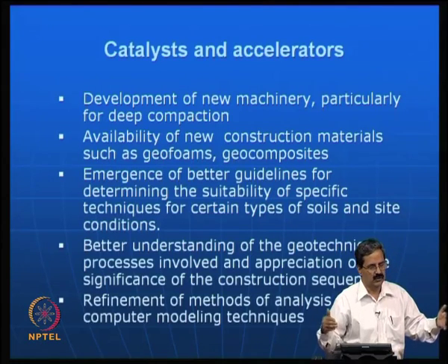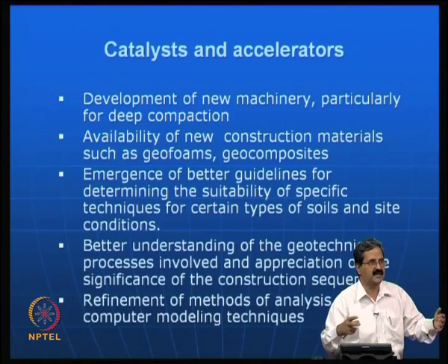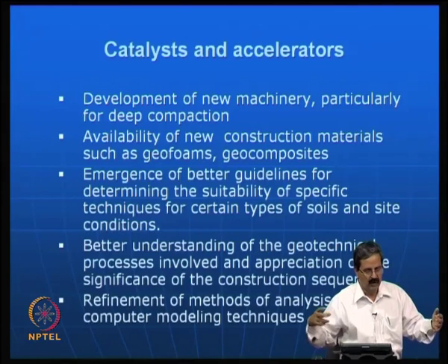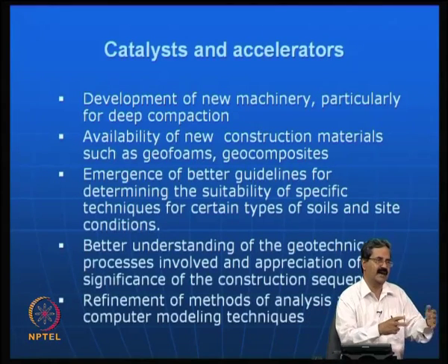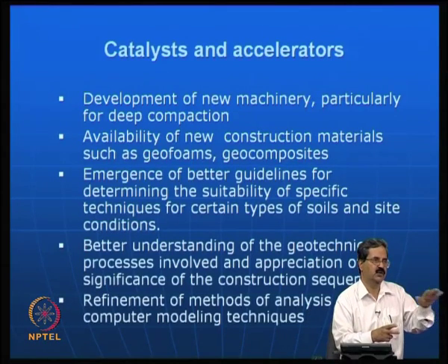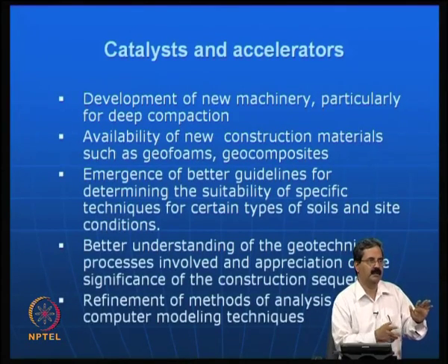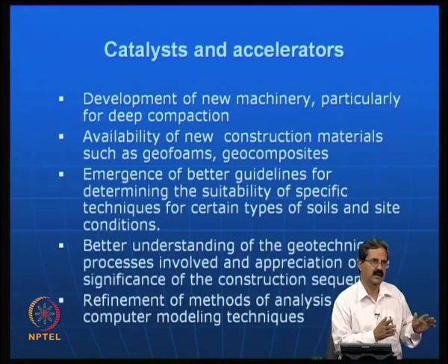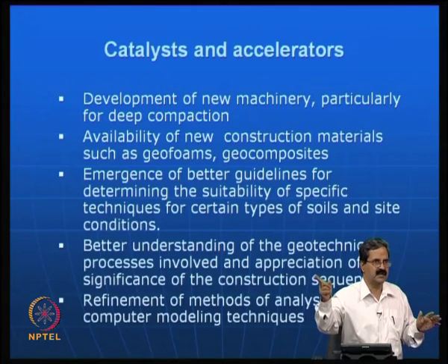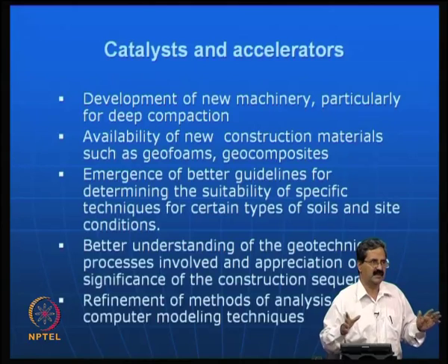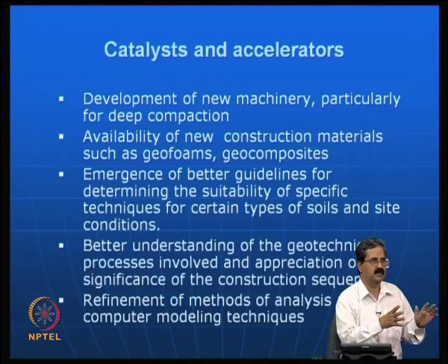So, for which you can use what is called trenchless technology, where you can push a pipe in without disturbing the traffic. You do not need to disturb the road and traffic at all, you can just push a pipe, it is called pipejacking. Actually our own underpass was done like that, without disturbing the traffic one can push the small pipe.